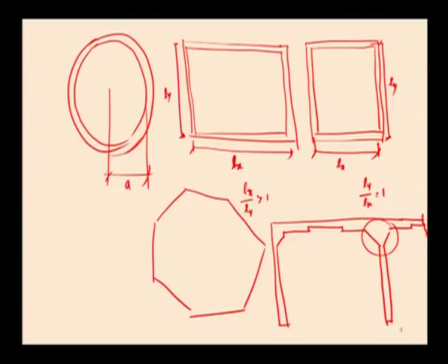So, in order to resist the moment as well as the shear forces, the column over the support has to be enlarged. Normally, the maximum bending moment developed at the support is a negative bending moment, and the moment developed in between the supports is called the positive bending moment, which is somewhat less than the maximum negative bending moment over the support.